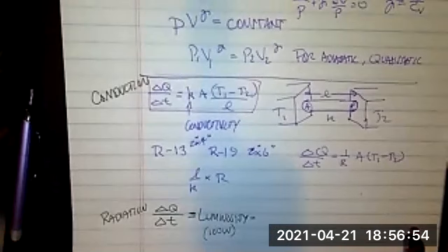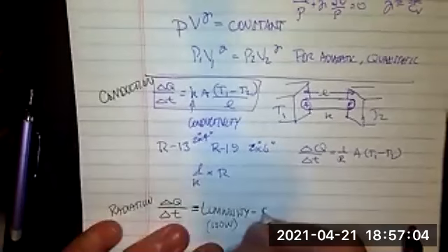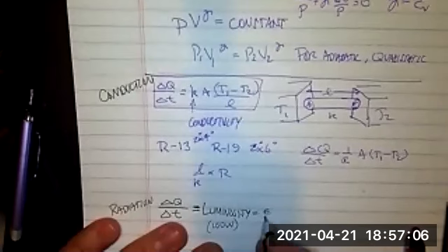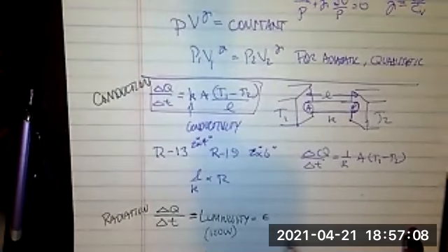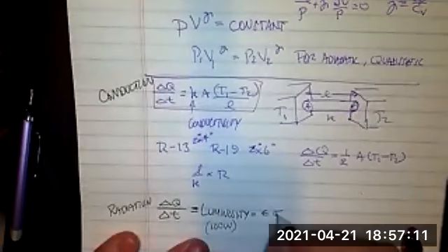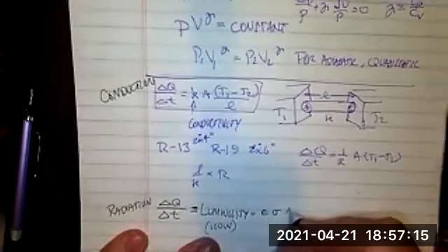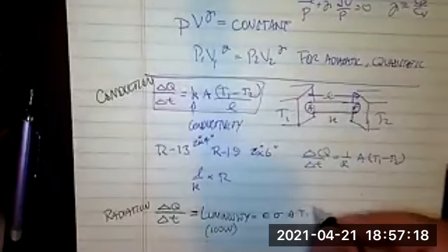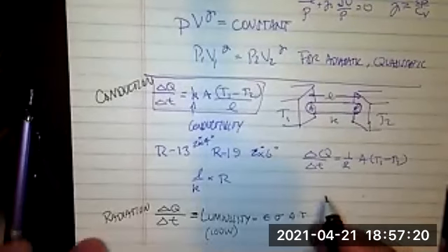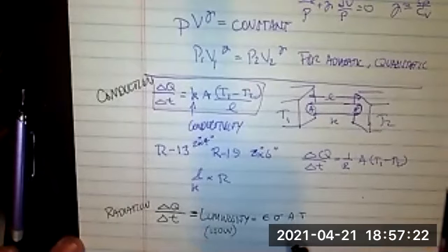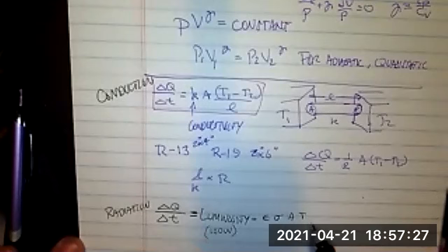But what we're saying is the Stefan-Boltzmann law says that the heat transferred per unit time is some emissivity constant, which your book uses epsilon for, times the Stefan-Boltzmann constant, sigma, times the surface area, times temperature to the fourth. But here's the weird part. Remember, anything that has a temperature other than 0 Kelvin is radiating heat away to things that are colder.